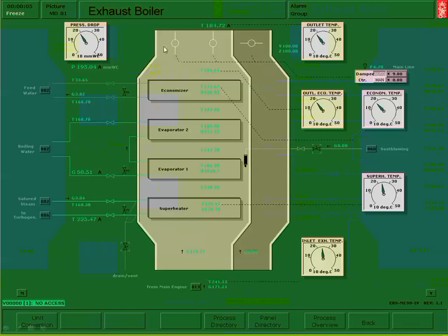The other thing on this is by regulating gas flow and bypassing some of the main engine gas around the exhaust gas boiler rather than through it, it slows the speed of the gas upward movement, and it's more likely for that to settle down onto the tubes, and you're more prone to an exhaust gas boiler fire. So in this scenario that I built, we are not really using these. They'll either be fully open or fully closed. They would also be a huge maintenance headache.